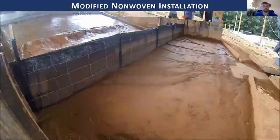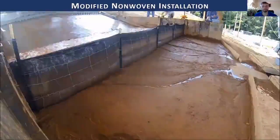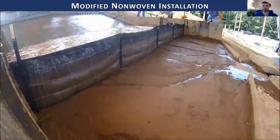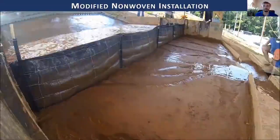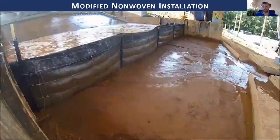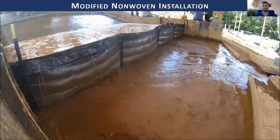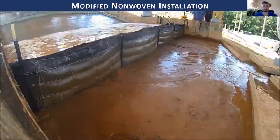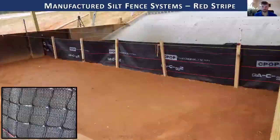So we made some modifications to the design. We changed out the smaller T-post for a larger T-post, 1.25 pound per foot. We reduced spacing from 10 foot to 5 foot. We reduced the height of the fence from 32 inches to 24 inches. And then we implemented an offset trenching methodology, which is how we attach the geotextile to the ground, into the soil. We were able to improve the structural capacity of the silt fence by doing this particular type of analysis.